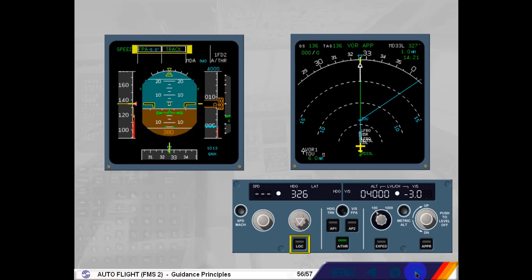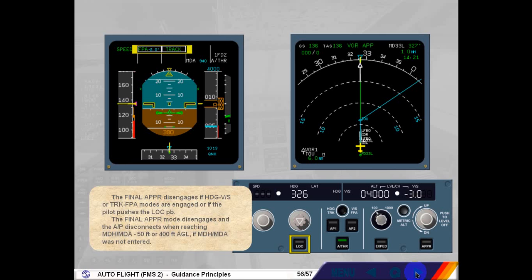The FINAL APP mode disengages and the autopilot disconnects when reaching MDA minus 50 feet, or 400 feet above ground level if MDA was not entered.